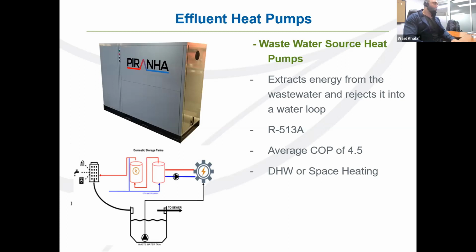So you have sump pumps or wastewater pumps. Those will be the same types of wastewater sump pumps that you'll have to maintain. So you have them on a chain, you pull them up, you inspect the probes and stuff like that, at a regular cycle. If I look at the heat pump itself, inside this heat pump, there's a big stainless steel tank. That's a big open tank, and that's where the wastewater comes in.